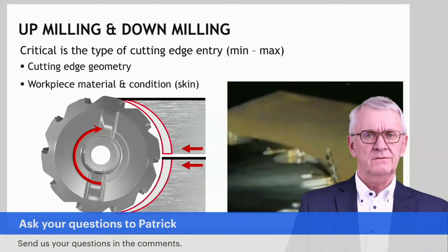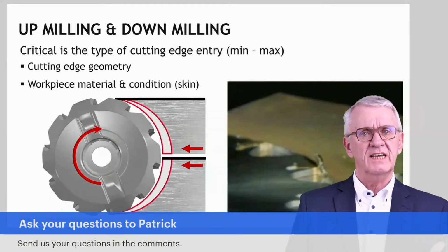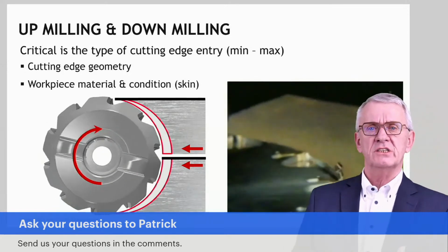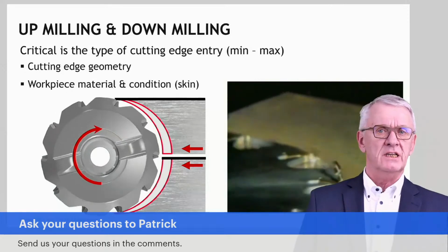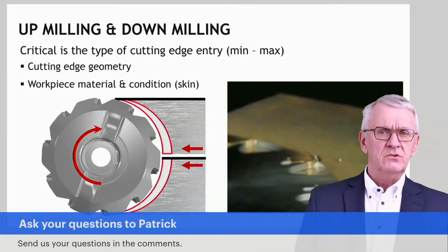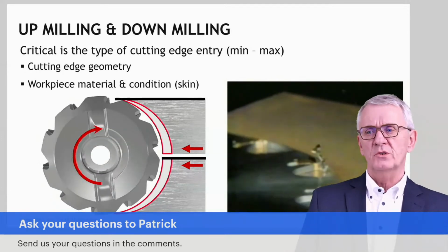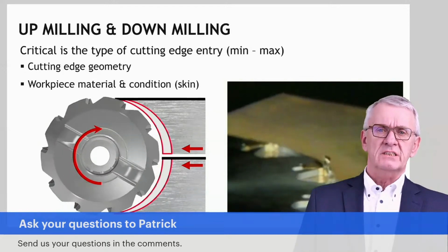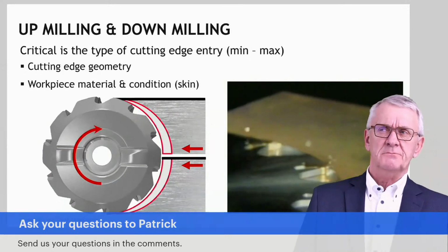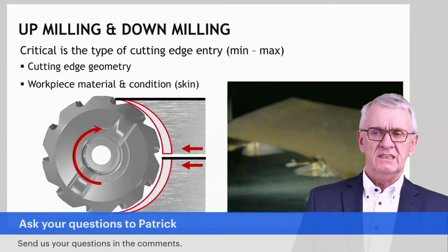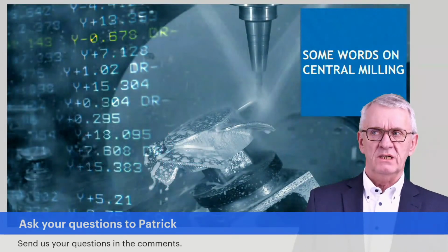Think, for instance, if you have to machine superalloys, strain hardening materials, where you push a cutting edge each time again through a strain hardened layer which has been formed. In general, try to avoid this. The opposite situation, where a cutting edge cuts from a certain thickness to thickness 0, is less unfavorable for a cutting edge. So that is what we have to bear in mind now.